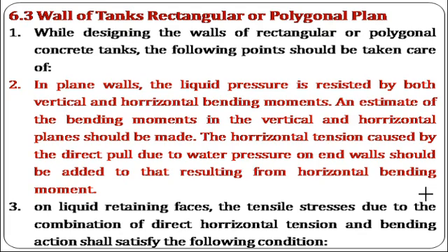The horizontal tension caused by the direct pull due to the water pressure on the end wall should be added to that resulting from the horizontal bending moment.